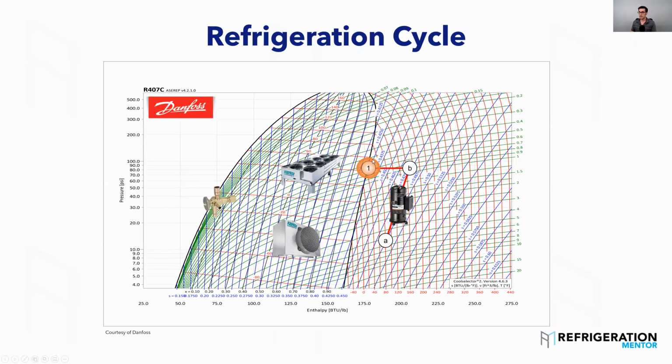Desuperheating, boom. Then we hit, what point is this? We talked about it many times. This line right here, this is all vapor. The dew point, yes, excellent. So we hit the dew point. Now right when we hit the condenser, what's happening? Condensing. We got droplets coming out of that refrigerant. You got to think of that like you're the refrigerant. As it goes through the condenser, it continues to condense, and then what?